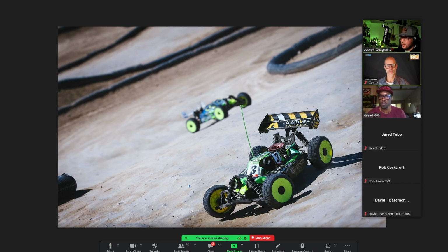Suspension movement doesn't cause load transfer. This is something that people often misinterpret. A go-kart that doesn't have any suspension has load transfer. You can't stop load transfer by stopping the chassis from moving. Load transfer is a separate thing from suspension.